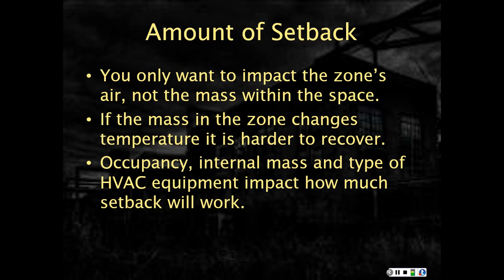I know it's going to take a long time to recover when fall comes, but I'm okay with that because I'm going into a prolonged period of unoccupied. But if the unoccupied period is not a fair length of time, then I have to be careful that I don't impact the mass within the space. And the more mass of the items, the more danger I'm in because they don't recover fast. If the mass in the zone changes temperature, it's harder to recover.